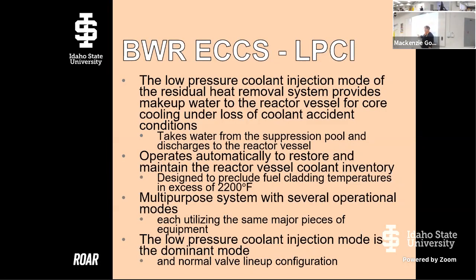We talked about that fuel cladding, right? So it melts somewhere up around 2200 Fahrenheit, a little higher. So this is the temperature that we have to keep the clad from reaching. So all of these systems are designed with that in mind, okay? This has multiple modes of operation at a boiling water reactor.